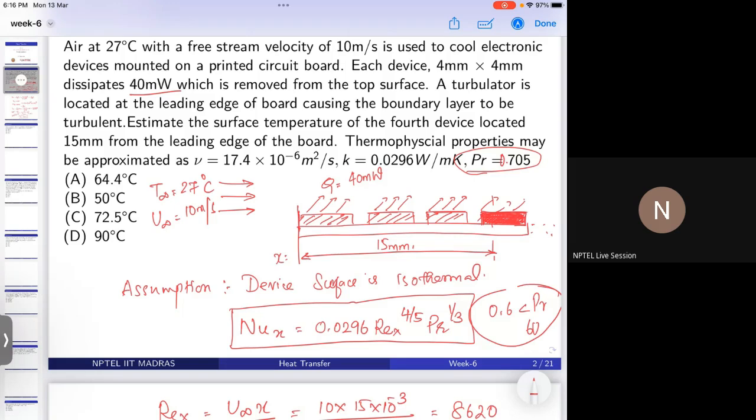Most of the cases we are dealing with Prandtl number in this range, like air. The low Prandtl numbers go to liquid metals and so on, so there we have to use other equations considering the lower Prandtl number. And I think there is one equation which is true for any Prandtl number range, so you can check on the web.